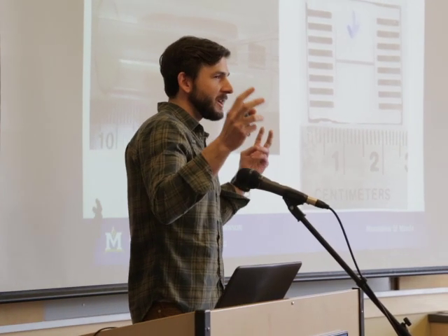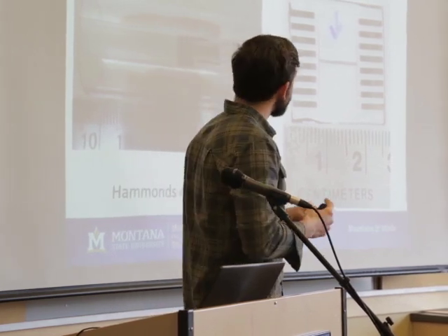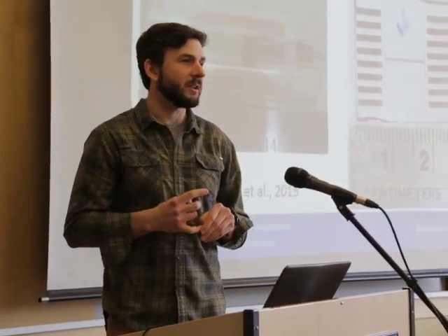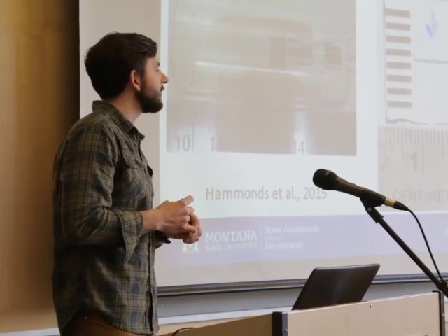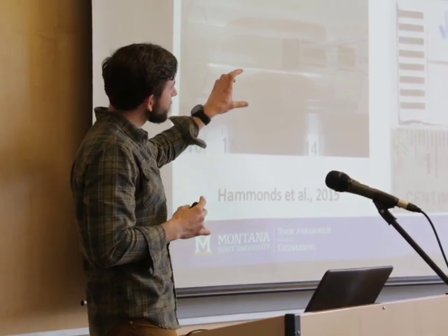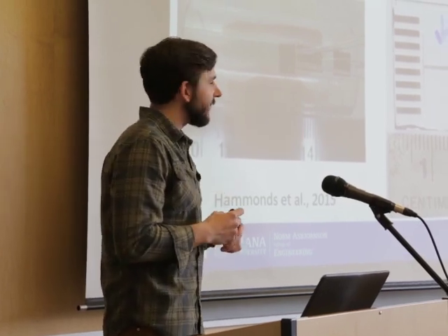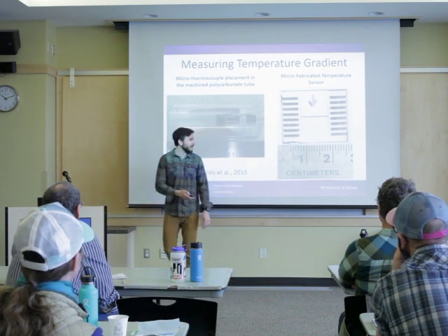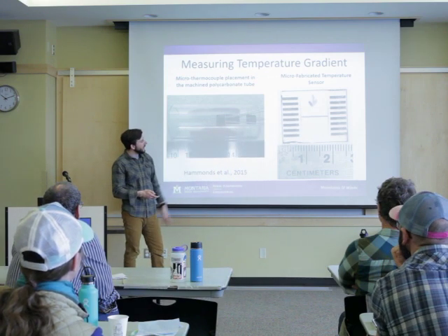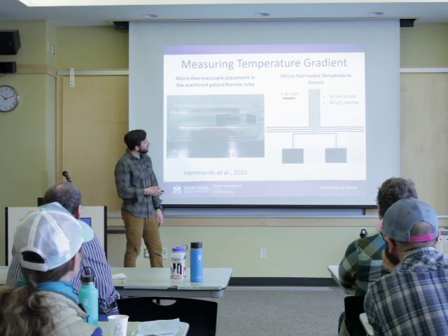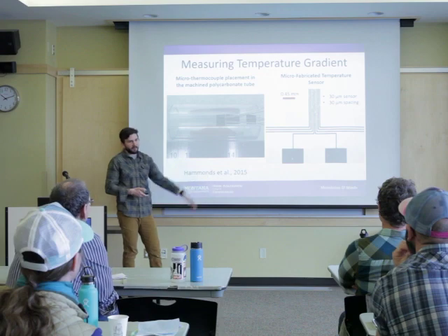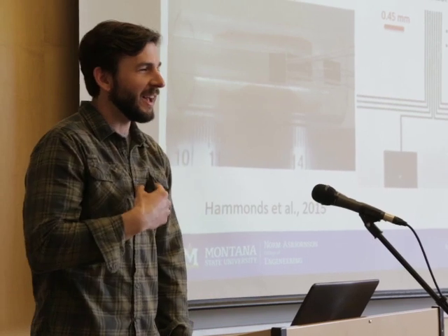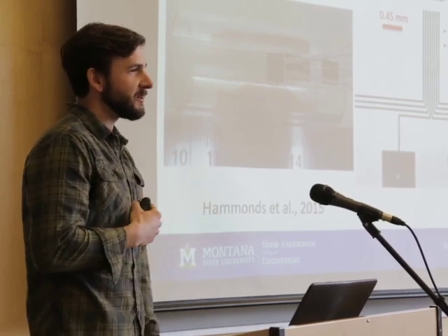What I'm going to call the next generation of temperature sensing is these microfabricated temperature sensors. Dr. Warnott, who is one of the new professors in mechanical engineering that Kevin showed earlier, is fabricating these temperature sensors on such a fine scale that this right here is 8 measurements. I'm actually going to zoom into it. That whole piece is 2.5 centimeters, but you zoom into it and there's 8 measurements over 0.5 millimeter. So these are essentially thermistors.